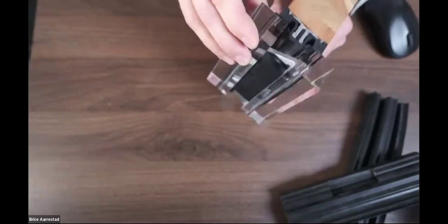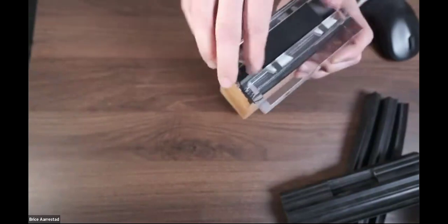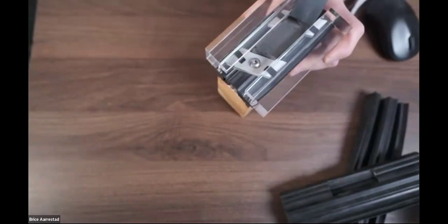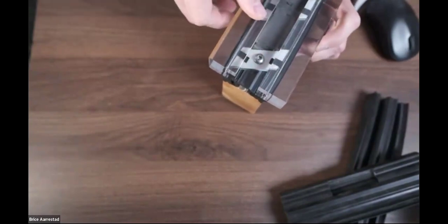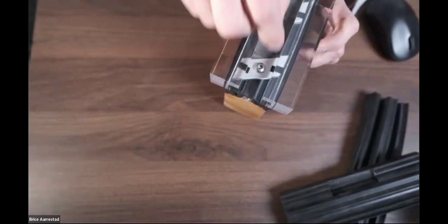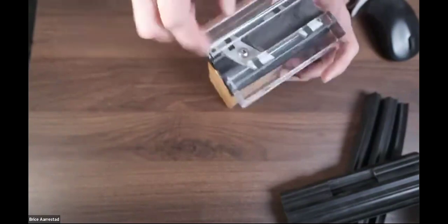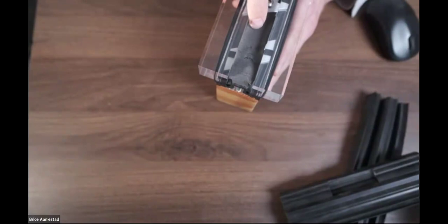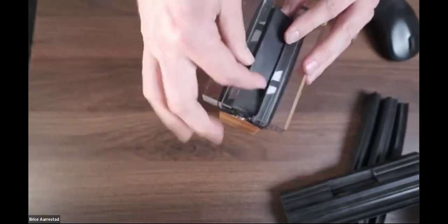This is just acrylic for demonstration purposes, but you're seeing there's a channel and then there's a toggle that is screwed into the base profile. It's twisted in order to lock it in place, and then it's finished with a rain screen sealant. There's also a neoprene gasket in here that acts somewhat like a backer rod for that sealant.